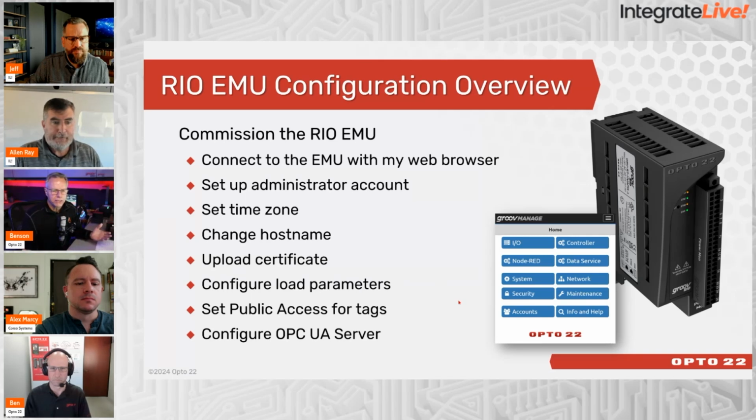Then I'm going to commission this device right out of the box. So I'll set up an administrator account, configure its time zone. I'm going to change the host name to something a little bit easier to remember than the default one that ships from the factory. I'll get a certificate uploaded to it. I'll configure the load parameters, set all the tags that we're pulling in to be public. Again, this device is a zero trust device, so nothing's available until it's configured, including the account and including any of the tags on there.